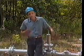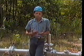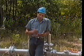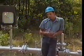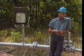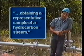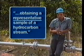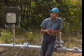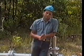In order to sell this gas, a way is needed to measure the amounts of each gas present in a particular gas stream. This is done by sampling. Now, sampling, as defined by the Gas Processors Association, is obtaining a representative sample of a hydrocarbon stream. The key word in this definition is representative. A representative sample is a small duplicate of the product as it flows through the pipeline.